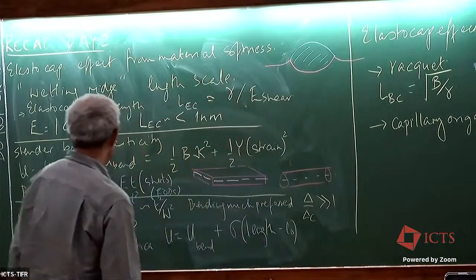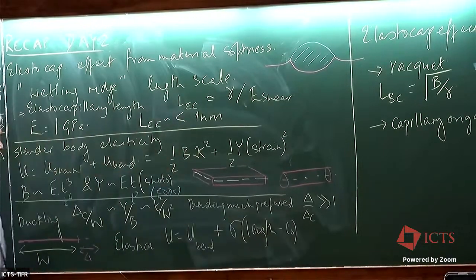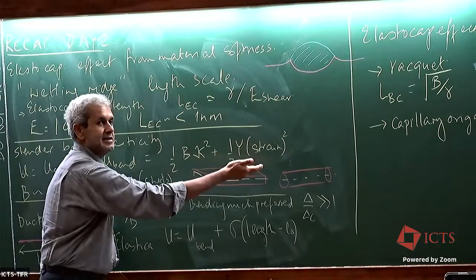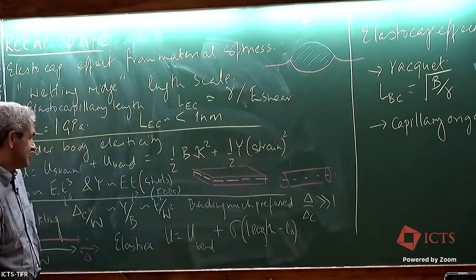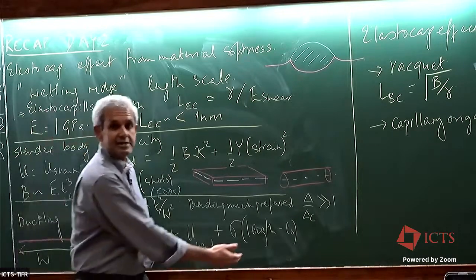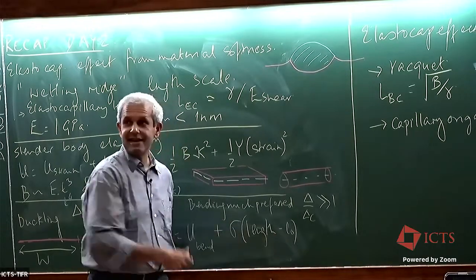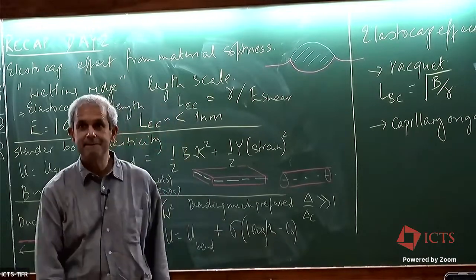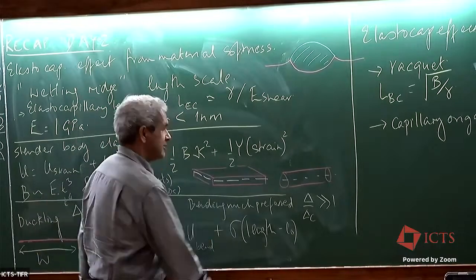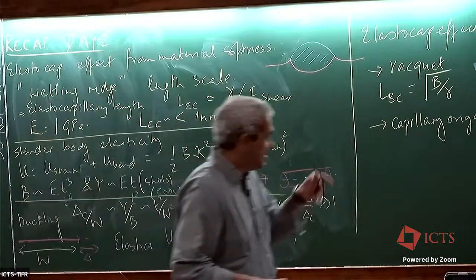Well above this threshold, the way you will deal with this is not by writing bending and stretching separately. What you'll do is say, I'm going to have a term that involves bending and a constraint that says I must keep my length, the length that you originally gave me. And the Lagrange multiplier that goes with that will end up being the tension on this object.